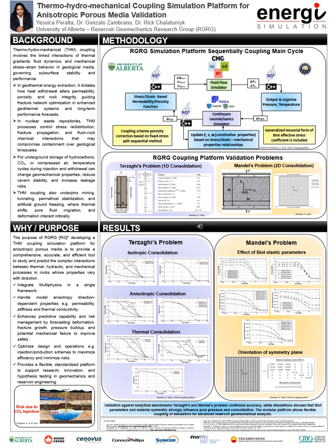The fourth is the vertical plane of isotropy. The isotropy plane is rotated vertically, illustrating how layer orientation affects stress and displacement. And the fifth case, the 45-degree rotation of the isotropy plane, producing complex rhombohedral deformation that cannot be solved analytically.